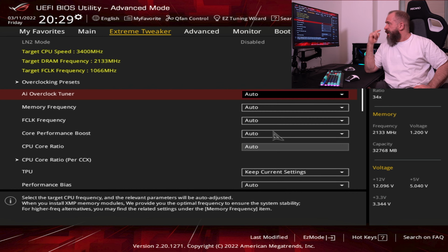At the very first, as you can see, the CPU is right now running with 1.45 volt on the CPU. That's kind of high. Maybe good for single boost cores and for OC and curve optimized settings where you are about to have high clocks like 5.05 gigahertz or something. This one, also my first CCX, the stronger one of both, is able to reach 5.25 gigahertz on 6 cores while it's playing with precision boost and with the curve optimizer on the right settings.